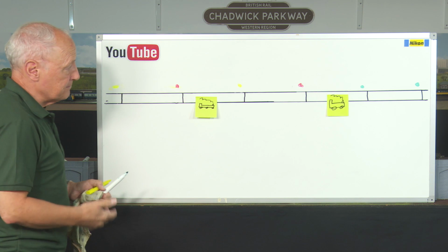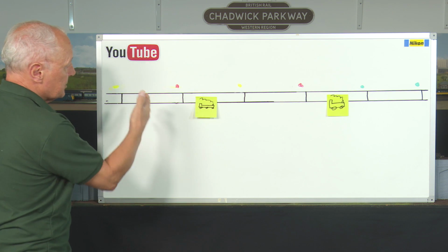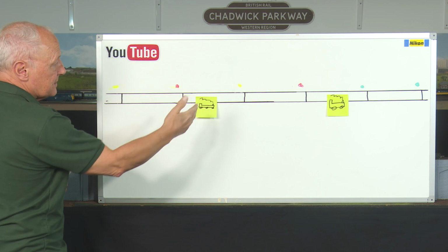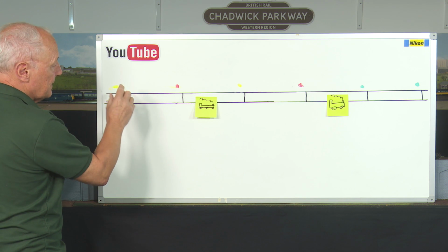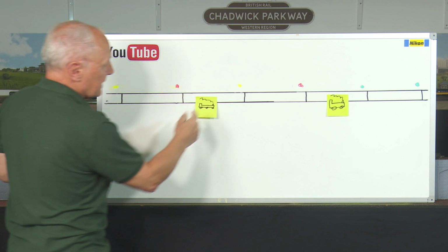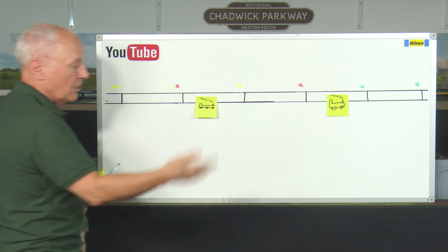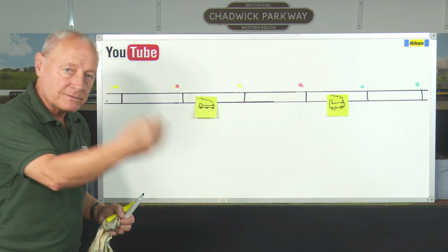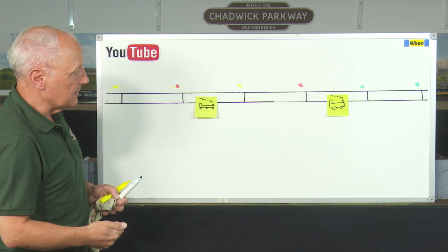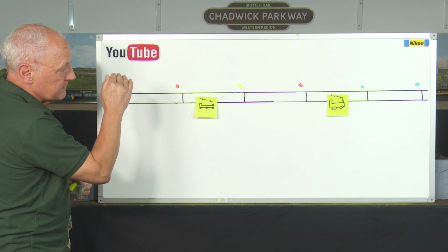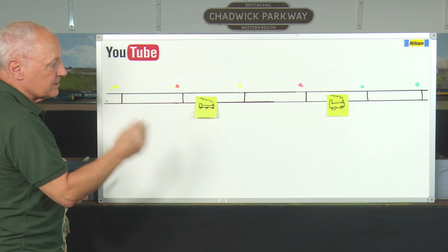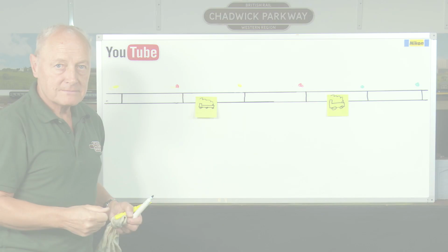I think it's pretty straightforward, and all it shows you is that the automatic signalling, because of block detection on the network, will tell the system that the following block is either occupied or clear, and the block in front of that may well be occupied or clear. So you build up some safety element based on time and distance.